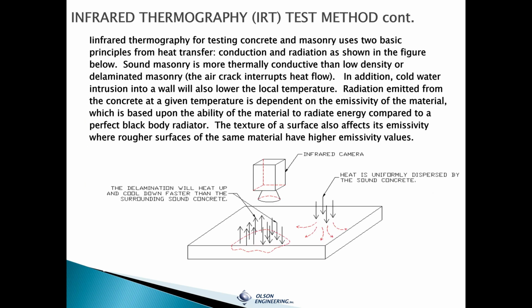What we're literally looking at when it's delamination, particularly in bridge decks and buildings, if you have debonding of materials, you can see within the first, say, 3 inches or so, as the solar heating, you have to have some heating source. As it warms up in the morning, the thinner piece of concrete or masonry will heat up faster in the morning than a thicker piece because it's more thermal mass. So you see that as a hot spot in your results. And in the evening, it will cool down faster because, again, the thermal mass where the delamination anomaly is will cool down faster because it's thinner.